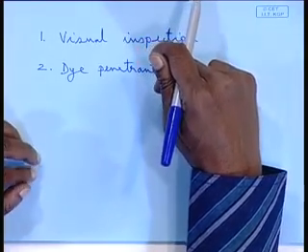Anyway, you may miss surface cracks unless it is a very wide and visible crack, right? So, to help visual inspection, one can take help of dye penetrant testing. Through using a kind of dye, it enhances your capability of visual inspection.